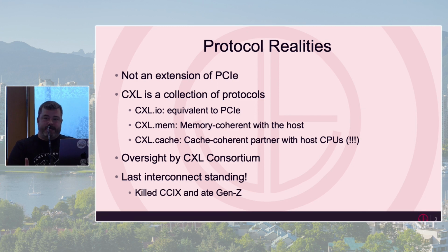So CCIX kind of died. People just got less interested in it and hopped on the CXL bandwagon. And then Gen Z actually got eaten by CXL. Last year, all of the IP transferred over, and lo and behold, all of the fabric management and RAS that was in Gen Z showed up in CXL 3.0.